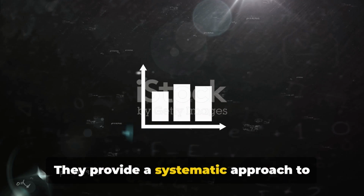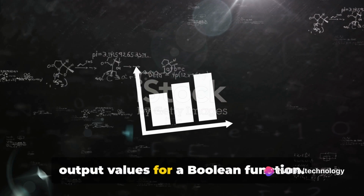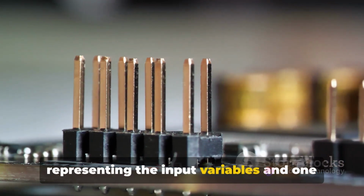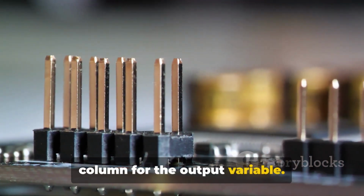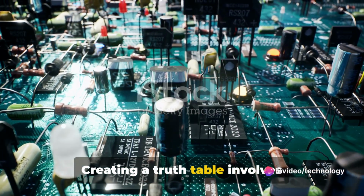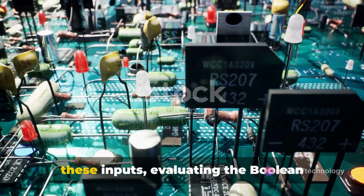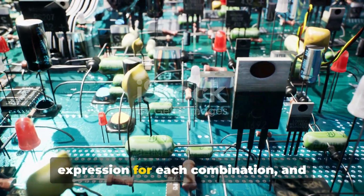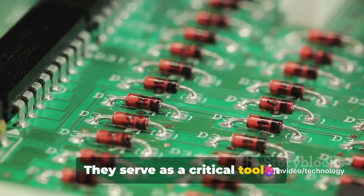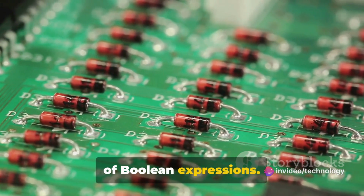They provide a systematic approach to mapping out all possible combinations of input values and their corresponding output values for a Boolean function. A truth table is comprised of columns representing the input variables and one column for the output variable. Each row is a unique combination of input values. Creating a truth table involves identifying the number of input variables, generating all possible combinations of these inputs, evaluating the Boolean expression for each combination, and finally filling in the truth table. They serve as a critical tool in designing and debugging digital circuits and understanding the functional behavior of Boolean expressions.